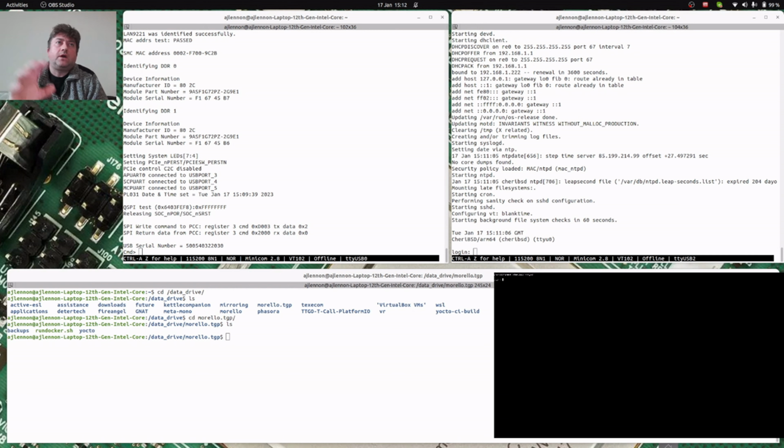So how is all this wired up? Well, we've got the physical box that I've got here. That's connected through a USB connection to my system, and that is enumerating as a number of different serial ports which output different kinds of information. Two of those we care about: there's an underlying command shell that we can use to manage this Morello system, and then there's the more usual boot shell that you would see when your system comes up. And down at the bottom right, you won't be able to see very much, but this is actually a capture of the HDMI output of the box. So that's what you would see on an actual display.